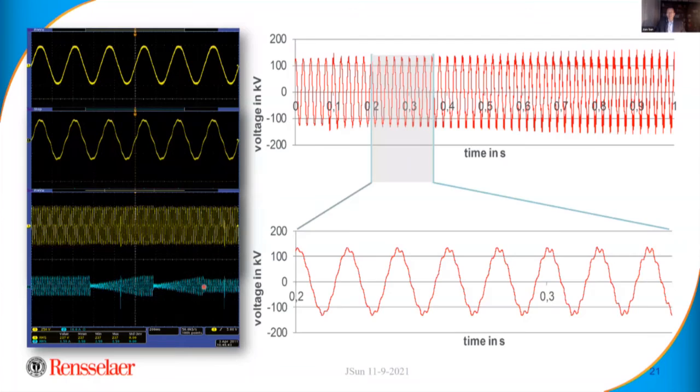It's not unstable yet, right? But it's an indication of lack of stability margin. When we further increase the inserted impedance, the instability occurs. So the inverter cannot be connected stably. It just cuts off. And then because we didn't disconnect, after a cycle or two, the inverter will start over again. We cannot sustain a stable operation. So this is a good example to show how the impedance, the strength of the grid, can impact the stability of the grid-connected converter.